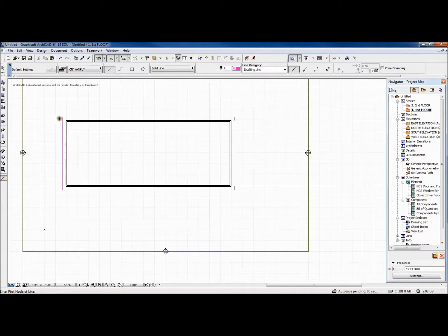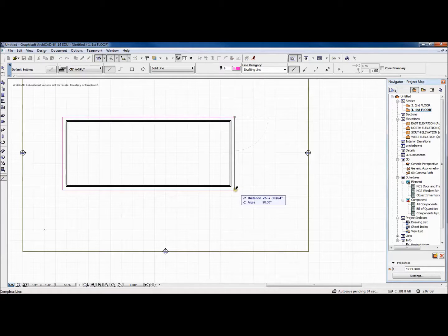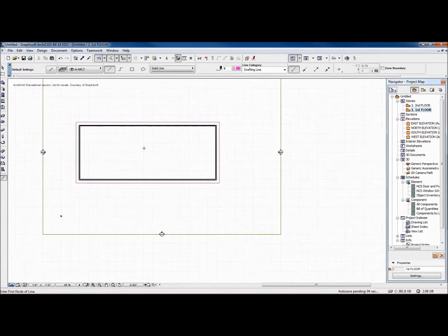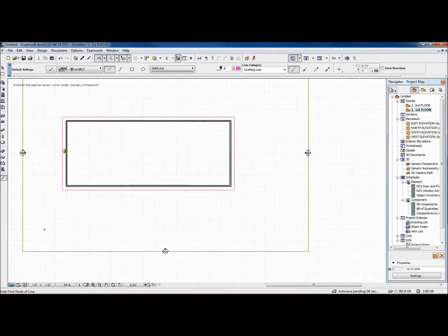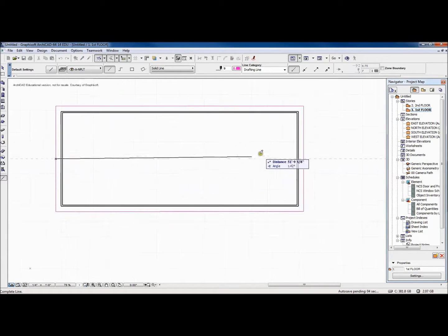Then I'll pick up my line tool once again and draw this edge and that edge, and then at this point I can go ahead and get rid of these points again, and I can put in the proper perimeter. So right now we have a 16-inch overhang. And so now we need to design the ridge board. Well, the ridge board, if I hover over this location, you can see the hash mark right there. So I can click on that to place, and then I can pull a ridge across in this direction.